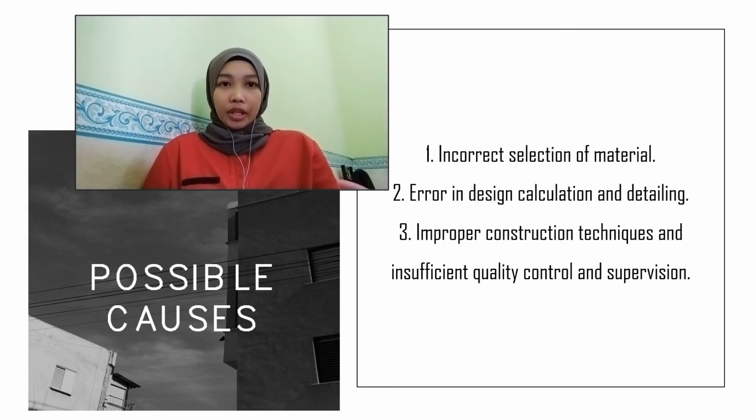Number 2. Error in design calculation and detailing. It is critically important to exercise great care while design calculation is performed. Otherwise, undesired events and expensive structural development may prevail. That is why it is advisable to conduct a complete design check to ensure that reinforced concrete sections, sizes, thickness, and reinforcement spacing and sizes are enough to support the most critical load combinations.